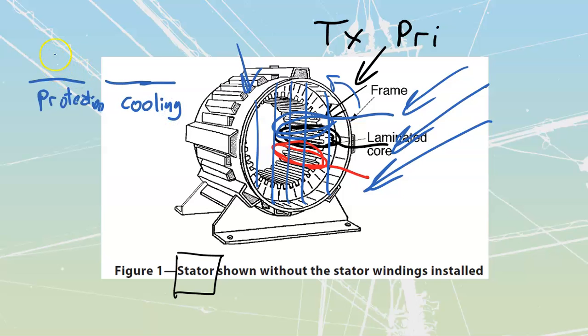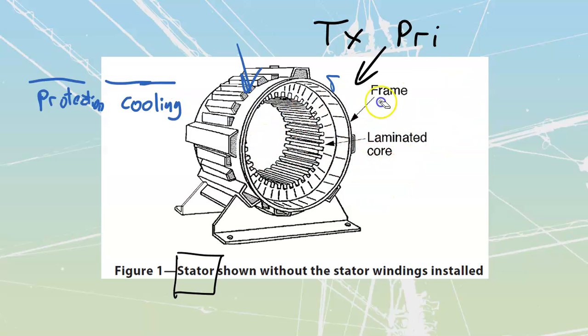And we don't have to have something. This thing could be skipped. If there's no protection, we wouldn't have to place anything inside there. If there's no cooling, we wouldn't have to place anything inside there. But you're going to see different types that are going to be placed inside there. The first one that we are going to have is open types of machines. Open types of machines do not mean that they're going to be sitting wide open. It just means that there's going to be some places for us to have air cooling that's going to flow all the way through.